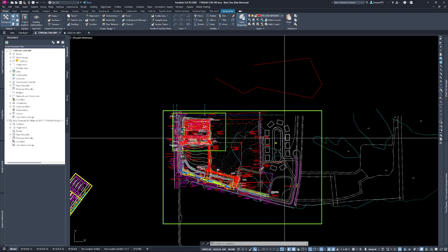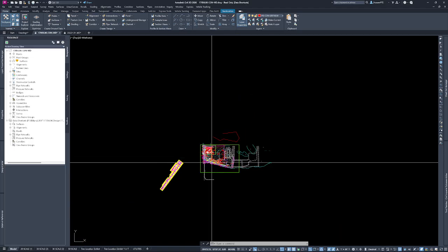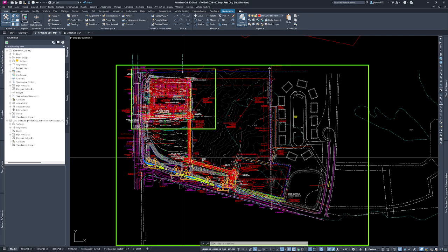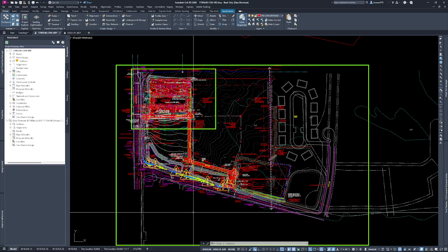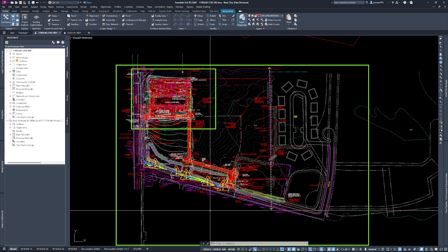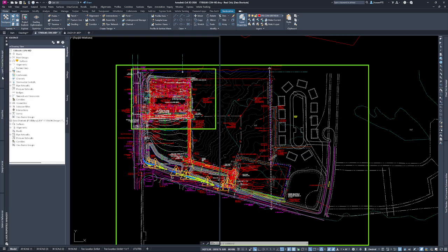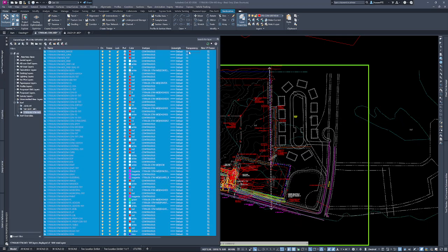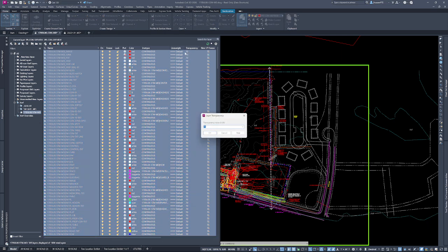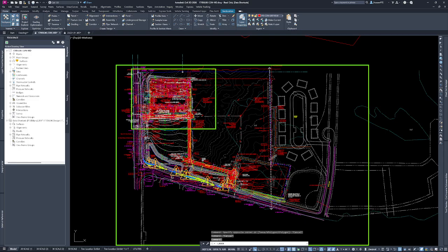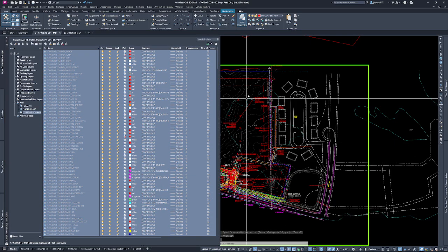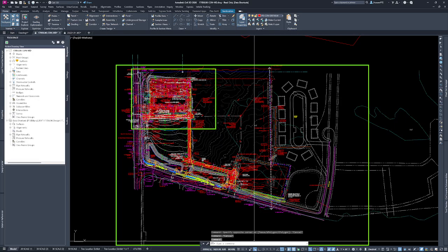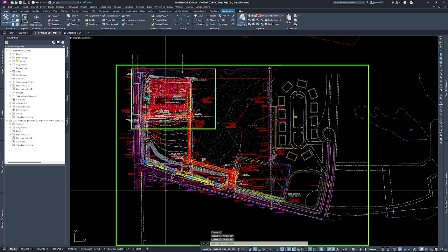I don't think I have an XREF really easily shown on this one. I think they're all turned off already. But that's one way of helping to clear up your visualization of your drawings and your projects. If you need to change it back, you can go back in there, change it back to 0, and everything should come back. The layer configuration transparency will affect plotting. The fade control does not affect plotting. Just keep that in mind.